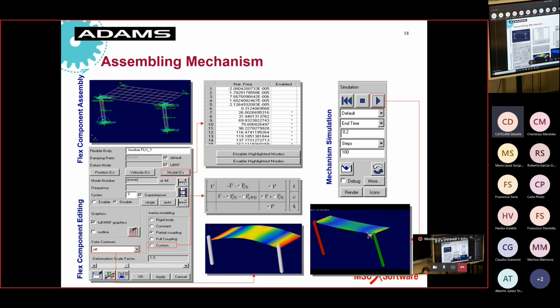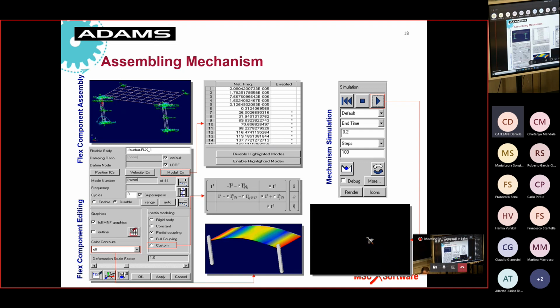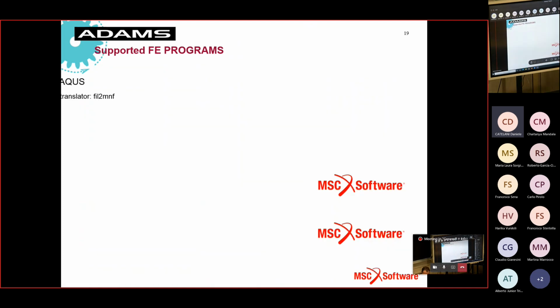In a dynamic analysis, fully dynamic analysis, or static plus dynamic analysis, which is not absolutely the same you have in a finite element code, in which the type of simulation is very limited to a small configuration around the starting configuration. In the finite element code, you are not able to simulate long simulations in a 3D space with no limitation, because the technology is different and the target is different.